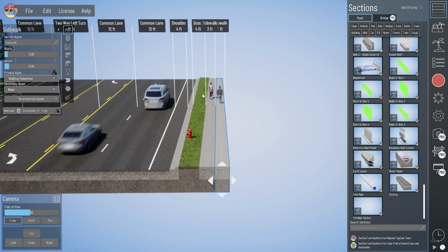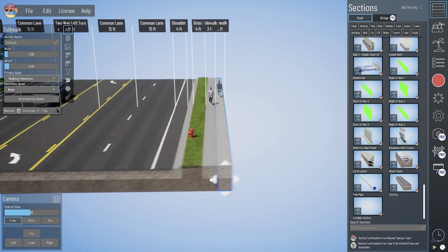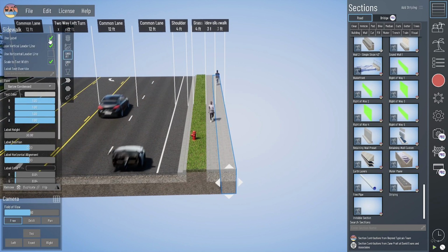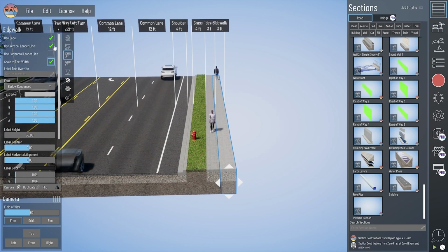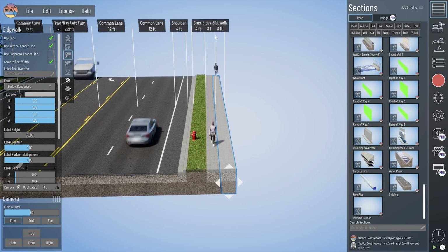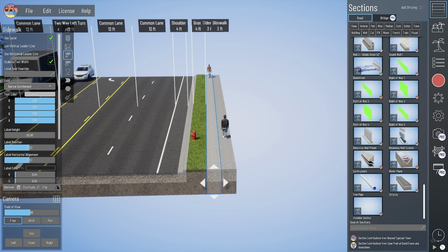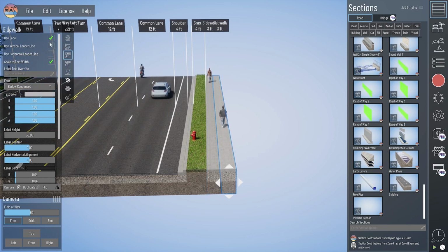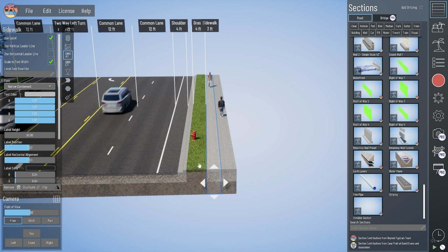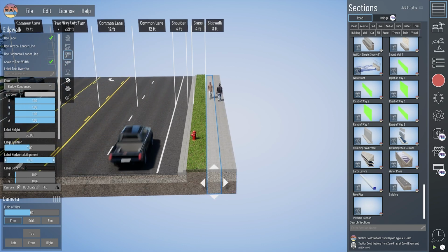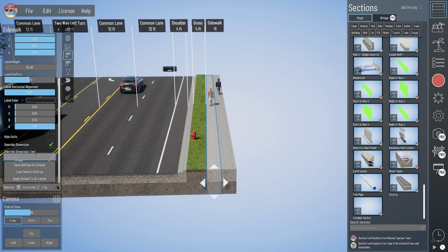I can go ahead and show 2 3-foot sidewalks next to each other, and then we can play with some section label overrides to turn a lot of those lines off. So we'd need to turn off leader lines for both of these elements to get that leader line out of the center of that section. And we can turn a label off at the top and use the other one with an override and change its position to show a sidewalk of 6 feet.